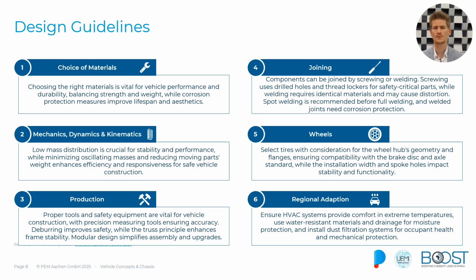In other regions, you probably need some weather protection because the weather is, let's say, bad in terms of humidity or rain, and therefore you need to protect your cargo, but also your people, and also parts and components of your vehicle. This might not only be related to water or humidity, but also to dust. So if you have very dusty regions that your vehicle will operate in, you would also need to think about how to seal off certain areas of the vehicle in order to keep it functioning over a long period of time and not need as much servicing as a vehicle, for instance, without some sealing.